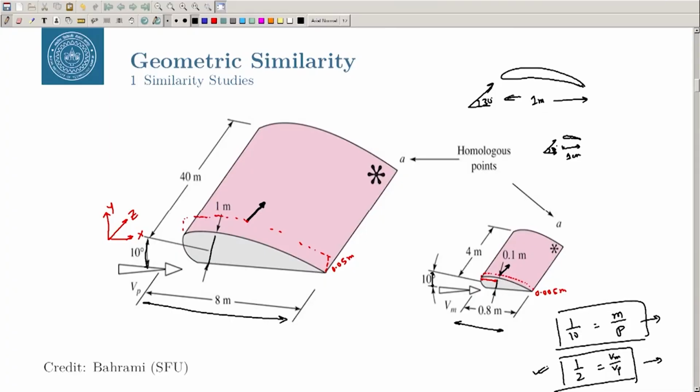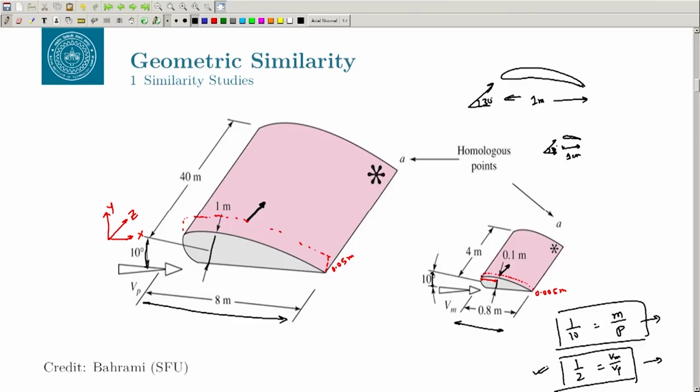If we are talking about laminar, both should be in the laminar regime, and if we are talking about turbulent, both should be in the turbulent regime. For transitional flow, particularly where the transition happens very fast, you have to be very careful whether you are in the laminar or the turbulent regime. You might have heard in your fluid mechanics course about the drag crisis, where the drag increases and suddenly drops as the regime changes. We need to be very careful about those things.